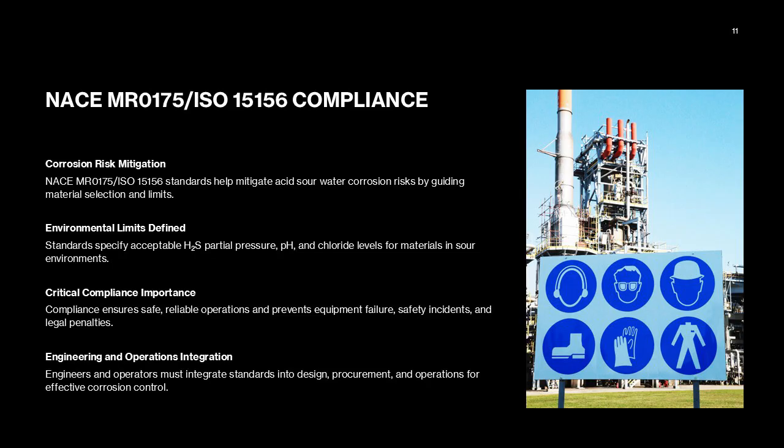Industry Standards and Guidelines, NACE MR 0175, ISO 15156 Compliance. To mitigate risks associated with acid-sour water corrosion, industry standards such as NACE MR 0175 or ISO 15156 provide detailed requirements for material selection and environmental limits. These guidelines define acceptable ranges for H2S partial pressure, pH, and chloride content, ensuring that materials used in sour service environments can withstand corrosive conditions. Compliance with these standards is not optional, it is a critical component of safe and reliable operations. Failure to follow these guidelines can result in equipment failure, safety incidents, and regulatory penalties. Therefore, engineers and operators must incorporate these standards into design, material procurement, and operational practices.